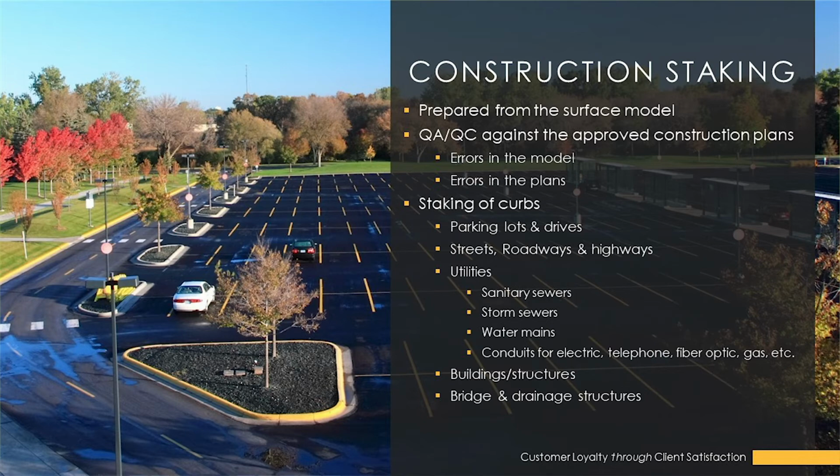At that point they're basically ready to truly get it down to the nitty gritty. There's typically not a lot of work to be done because the surface model has already put them pretty much at their subgrade. We're staking as a final kind of in-the-field QA/QC to make sure there have not been any missed points, or just as a final check so that the contractor can come through.